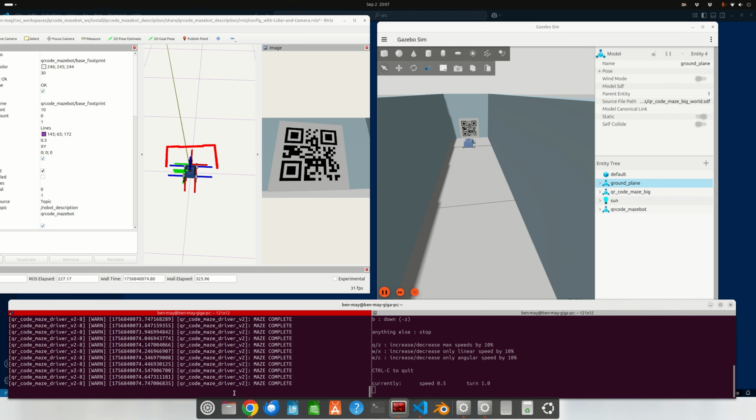So yeah, not the best program you'll ever see, but a lot learned building this one, and it really opened my eyes to how challenging it is to not just get the robot to drive through the maze without bumping into anything, but actually to get it to drive through gracefully without snaking around. And as I say, the next step for me will be to build V3 of this, if you like, which will use these lines of best fit and have a PID controller that's not just looking at distance from the walls, but looking at the angle the robot is relative to the walls.